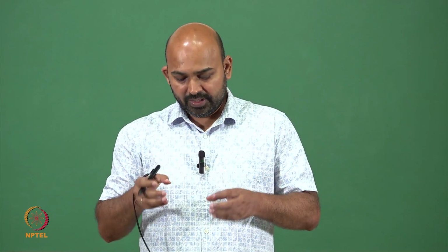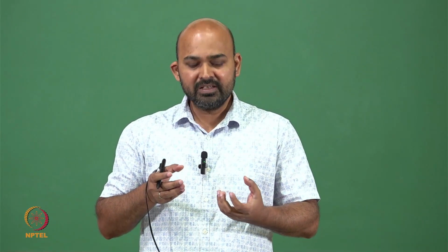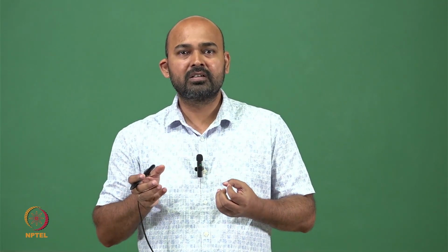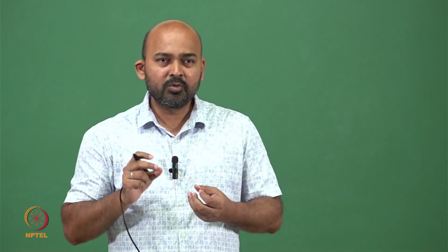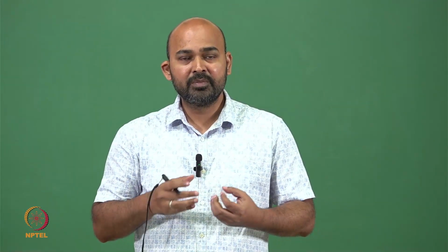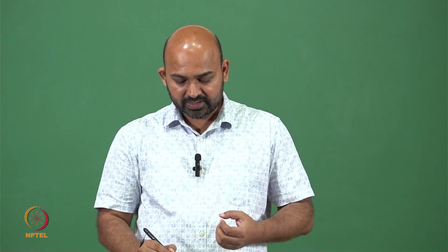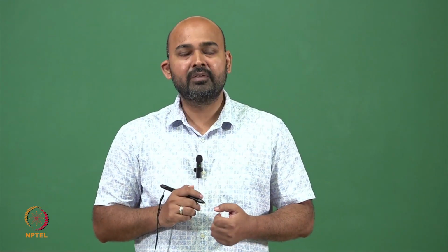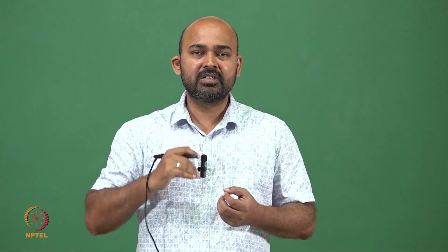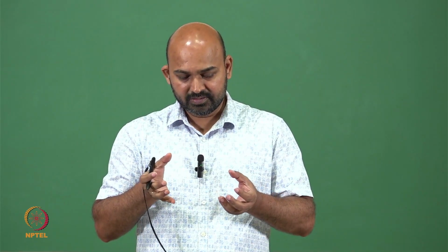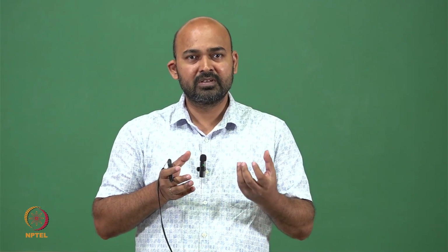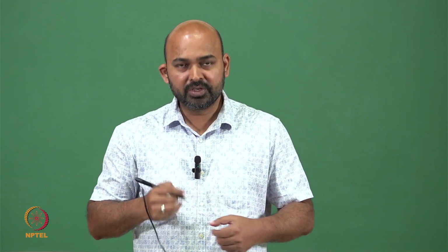This APD is a semiconductor device which detects the photon coming in and generates the equivalent electrical output. This electrical output is generally very small in magnitude, so we prefer to have an amplifier before processing this signal. So this is an electrical amplifier we put after the avalanche photodiode. This amplifier amplifies the signal. Then we can use some microcontrollers or our computers to process this amplified signal, and we can put it on the display.